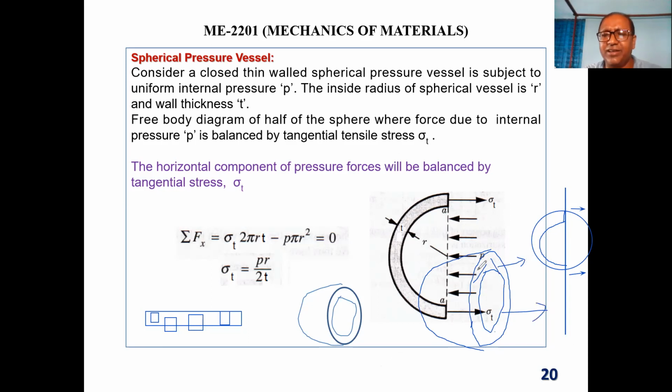So what is working on the left side? What force is working along this side? Along this side and this side, they neutralize each other. Just the side wall pressure is set. So how much pressure is working along this side? How can you figure it out? You press your hand from the right side. If I press this with my hand, it will be kind of a rectangle. So that area is the projected area. That projected area multiplied by pressure, you get the force. So the projected area obviously should be a flat circle, and the area will be pi r square.